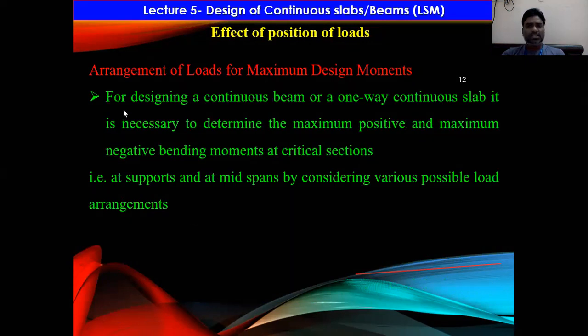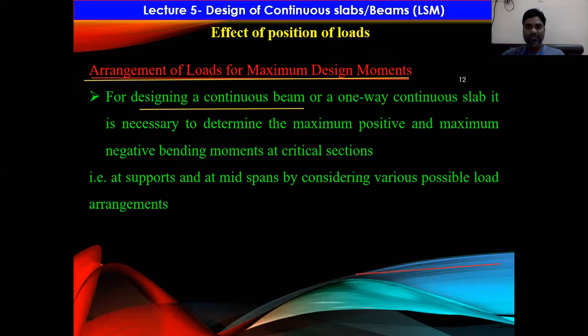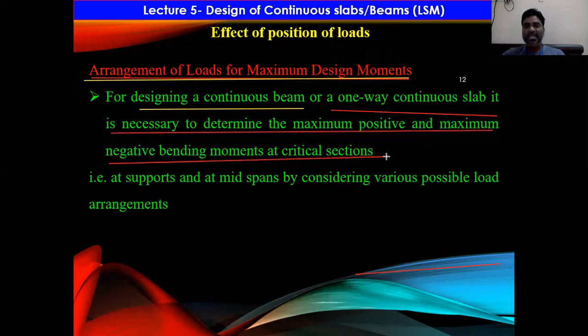And one more thing is to determine the maximum shear forces and bending moments. It is very important to arrange the loads to get the maximum shear forces and bending moments, right? So based upon the arrangement, you will get the maximum shear force and bending moment, right? That means in designing a continuous beam or one-way continuous slab, it is necessary to determine the maximum positive and maximum negative bending moments at critical sections,